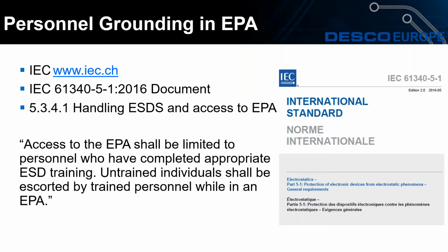Another requirement of the standard is that the access to the ESD protected area shall be limited to personnel who have completed training and have been retrained annually. So you can imagine if an employee from the office or someone who is not used to handling ESD sensitive devices comes into the lab without an ESD garment, for example, they might stand too close to the ESD sensitive devices on a workbench or shelving, or even handle the product without proper precautions. They could then damage the product unknowingly. So controlling access to the employees that have had regular training and their training is up to date reduces this risk.